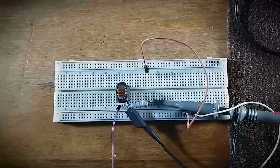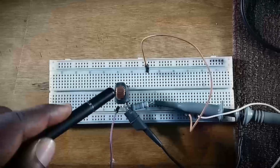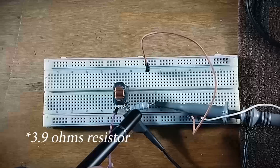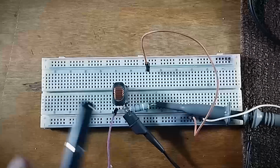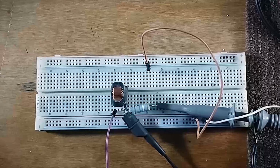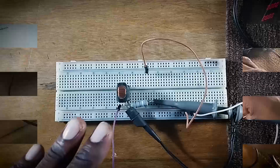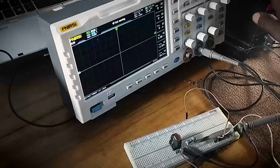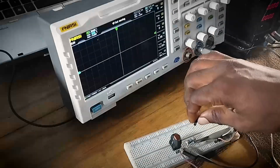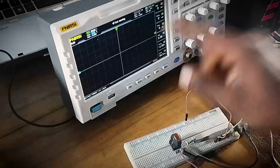Alright, so I have this setup here with a 300 microhenry inductor and a 0.39 ohm resistor, just two of them in a circuit. I just want us to see the exponential rise and the exponential decay of the inductor. I have an input coming in from my power supply. I'm going to make contact with the input, and then we're going to see what happens on the oscilloscope.